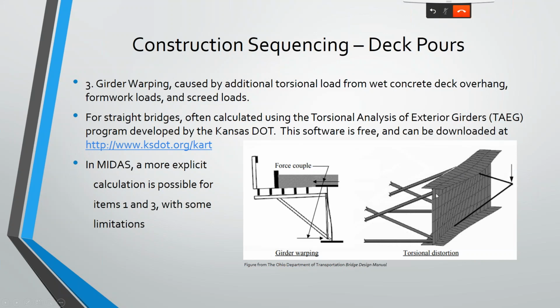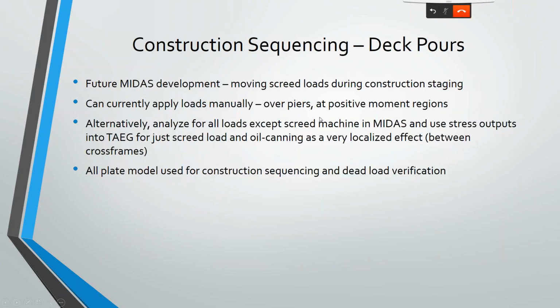Note, too, that a lot of this has to do with the localized plate elements and what's happening in the localized stresses. That's very important, and that's a reason why the plate modeling is much more accurate for rotations, is this localized rotation within this section, as opposed to seeing this as one piece with flanges and the web all together as a single unit.